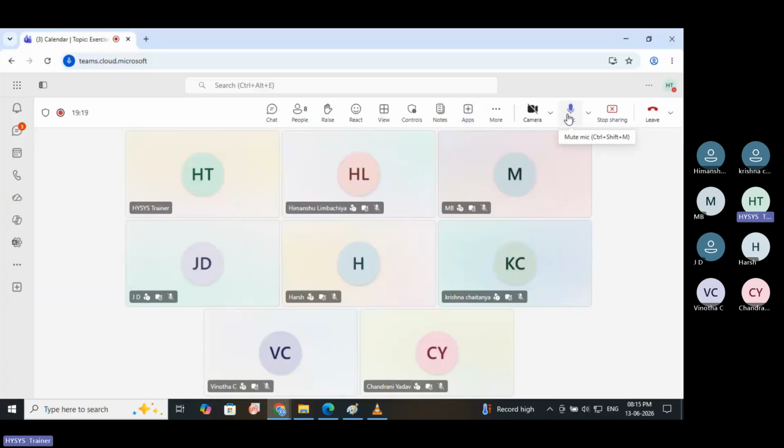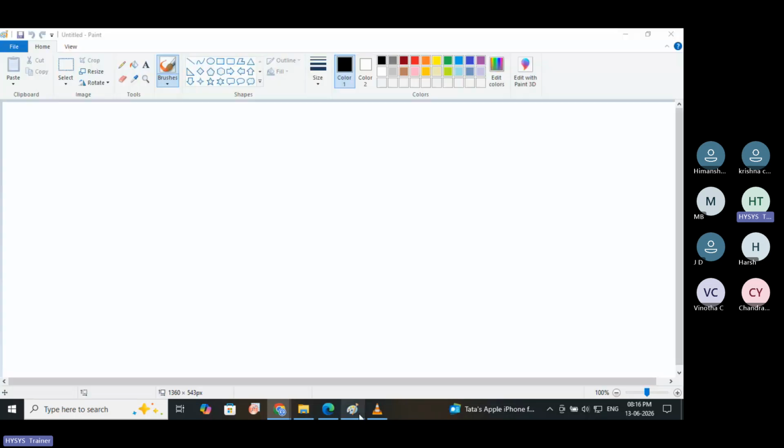So in this video, we have seen that sour gas, as we generally call it, which is nothing but the natural gas stream containing the acid gases, will be passed through an absorber, where the acid gases will be absorbed by the amine solution, which we will call the lean amine solution. The acid gases passed to that amine solution will then be removed using a distillation column, or a regenerator as we call it, and the lean amine solution is put back into the absorber column.